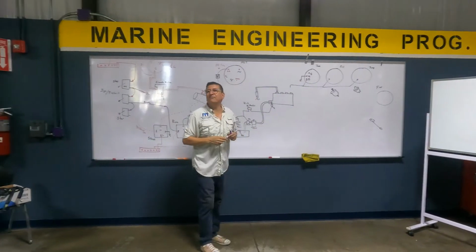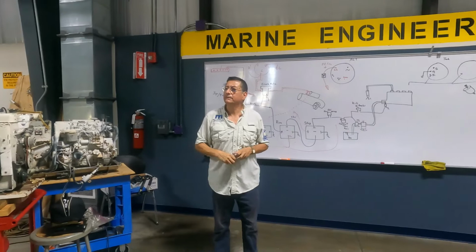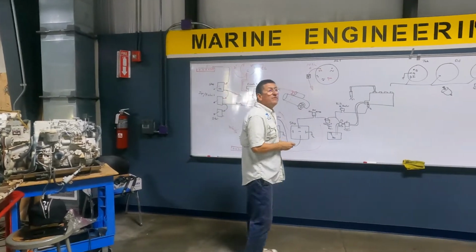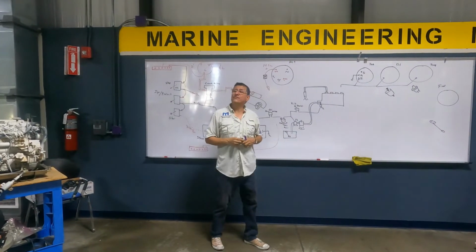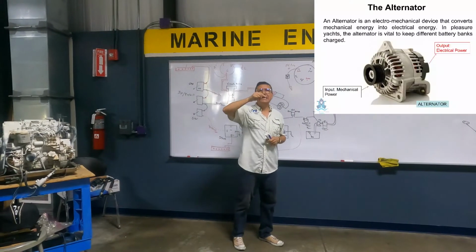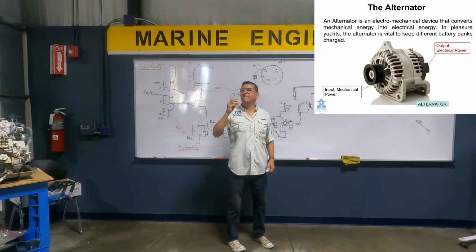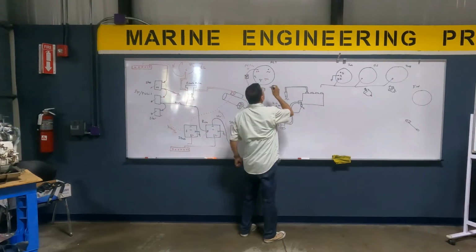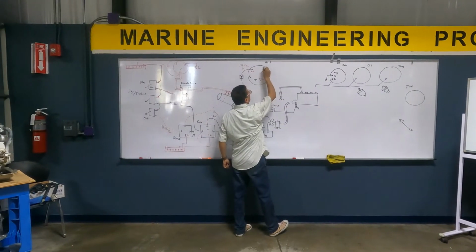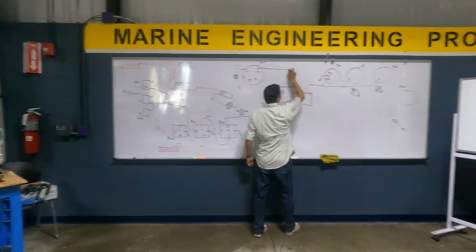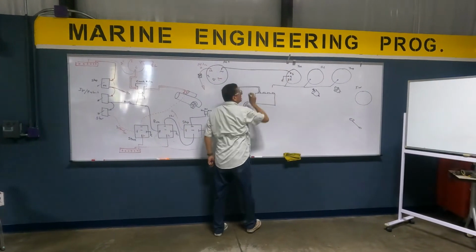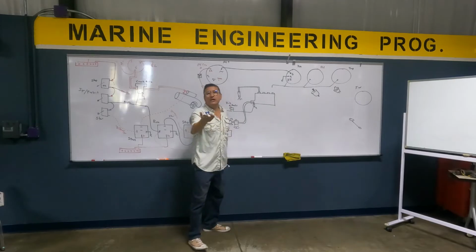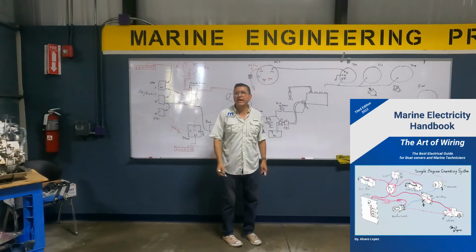And what is the signal for the tachometer, guys? Alternator. It's coming from the alternator. What output of the alternator? The AC. The AC output normally is covered with a piece of plastic. You remember that? And what is the color of that cable? Gray. What is the color? Check the book. Gray. I said gray.